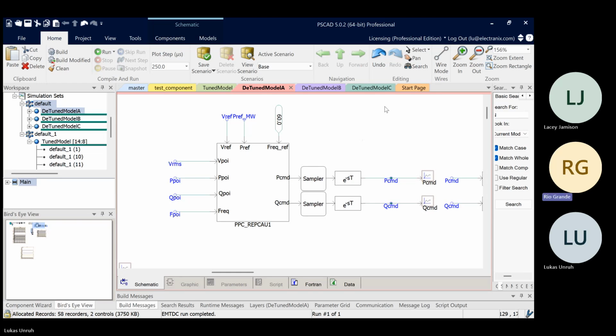So you have to find that middle ground of how we can do it with engineering margin where they're still going to be okay. A lot of times you just have to work with the systems that are there, and then you have to detune your PIDs or add a PID rate limiter. Right, yeah, rate limits for sure.